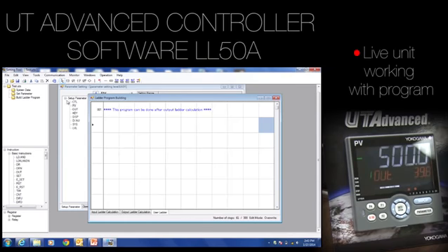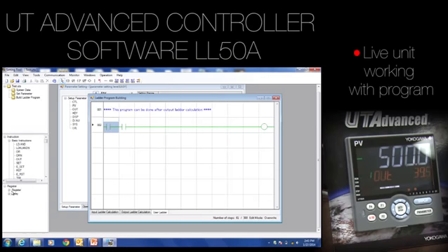So let's just build something simple here. Let's take this, and let's take that. That's going to be a main input. Let's have something flashing here, and let's have an output. This input here needs to be what we call always on, or in this program it's called PLS. So let's find a register for that.